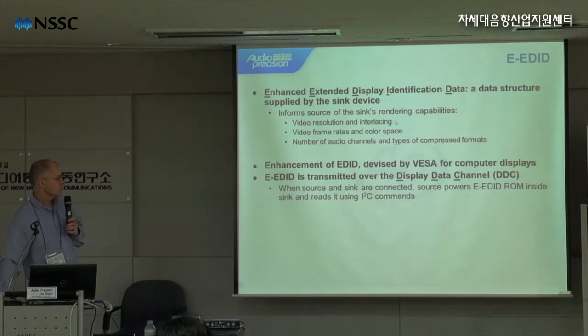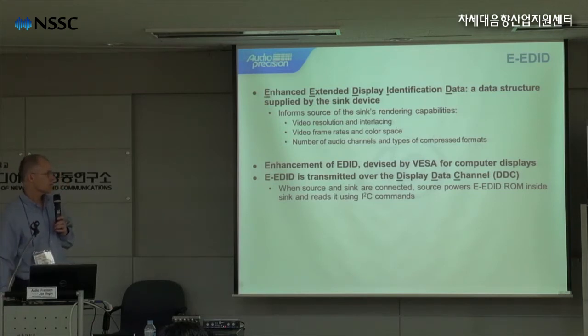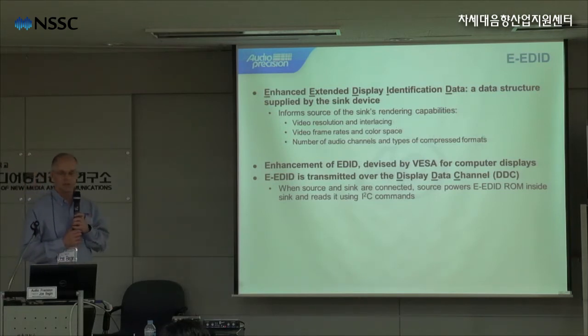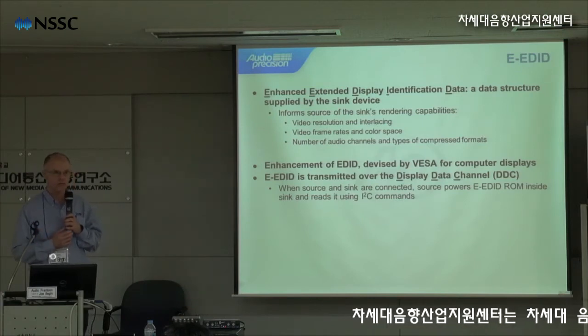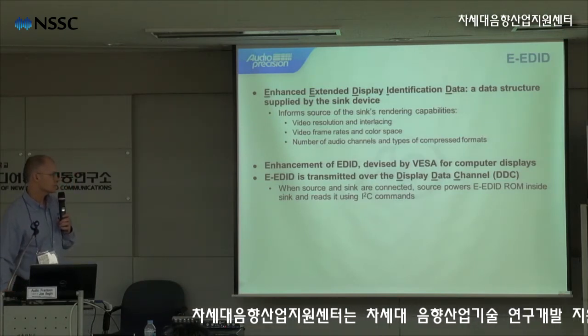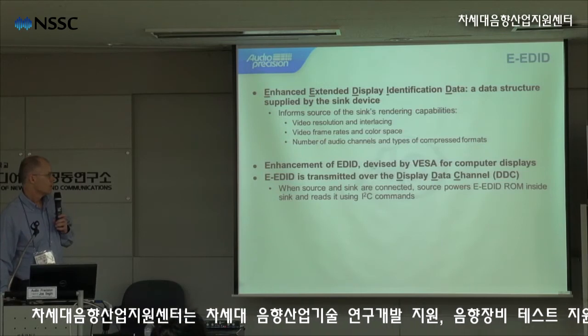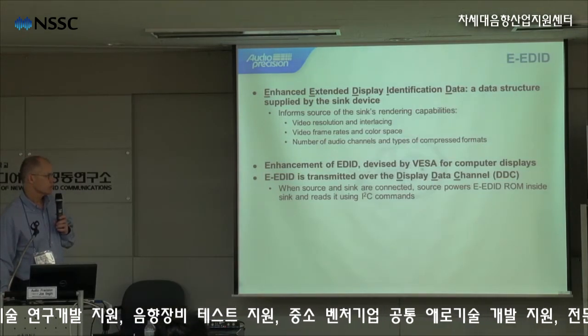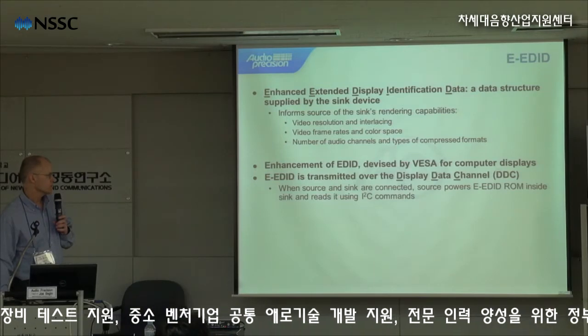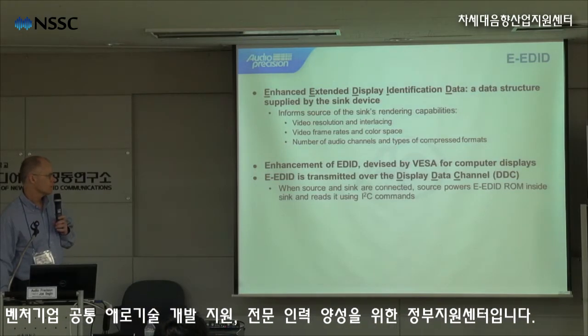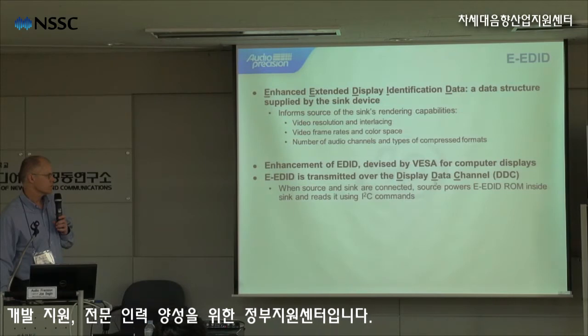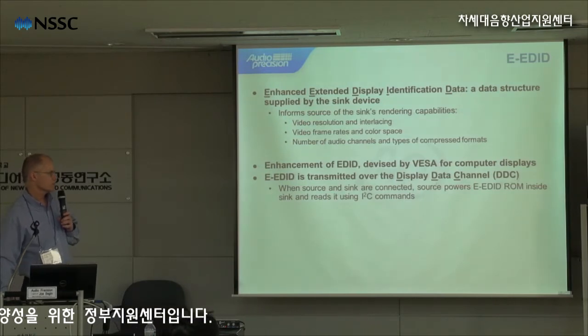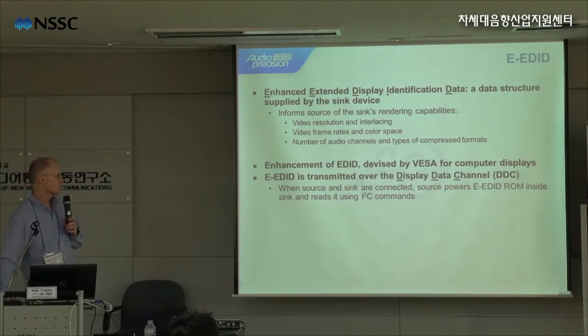And that includes the video resolution and the interlacing, the video frame rates and the color space that it supports, and the number of audio channels and the types of compressed or encoded formats that it supports. This enhancement of EDID was devised by VESA for computer displays, and the EDID is transmitted over the display data channel, which is one of the lines on the interface.